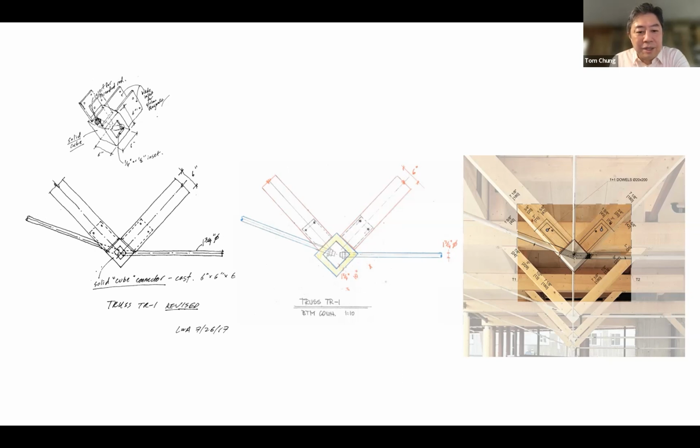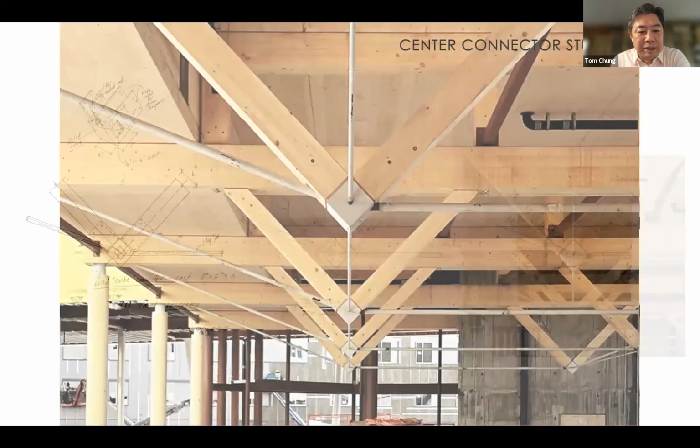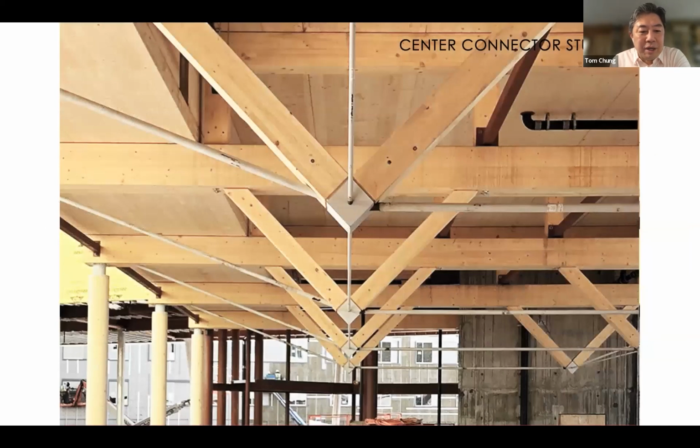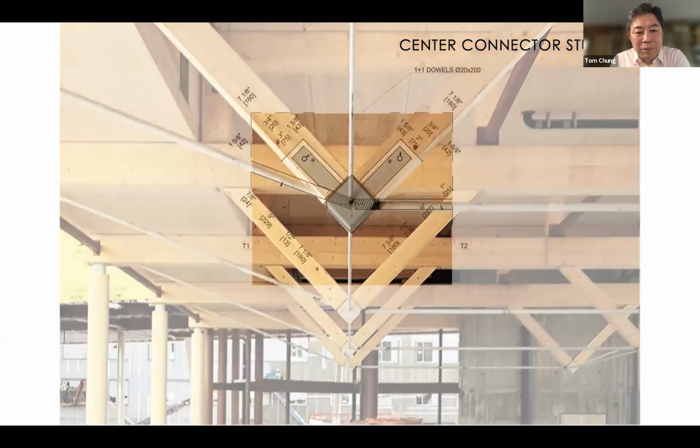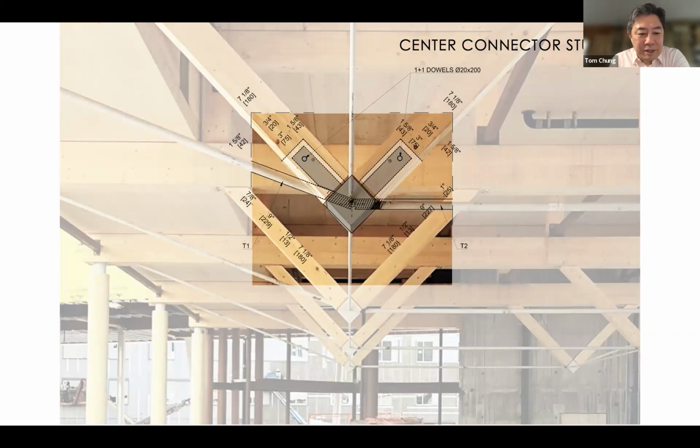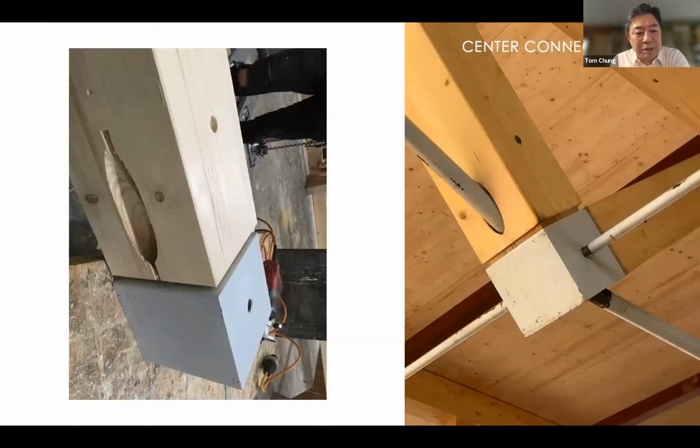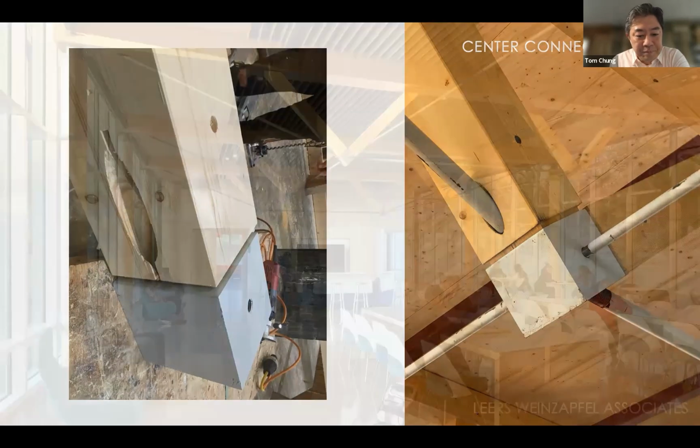And again, then using the ease of digital fabrication, the use of CNC machines to cut the wood, that joint became very simple, in which all of that cutting then allowed for the integration of the steel joint, as well as all of the connection tab that was necessary to be hidden between the members. You can see the cut of the wood with the CNC machines that allows for all of that connection to happen, and a detail of that just before the steel members get painted in the field, and an overall view.